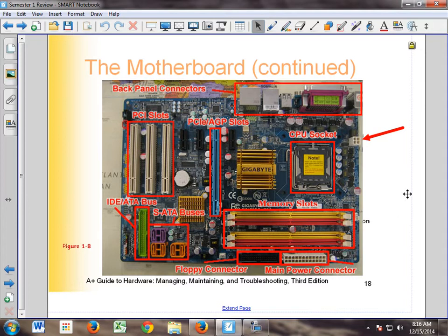That would really stink. Okay, we should be able to identify all these things on the motherboard. We went over this last time, but CPU socket, that is for what manufacturer of CPU? Intel, we can tell because of the hook on there, so it's an LGA slot. We've got a regular power connector, we've got an extra power connector. That is a what volt? 12 volt, right? And this one is 3.3, okay? Then we've got our SATA connector, our IDE or ATA or PATA.